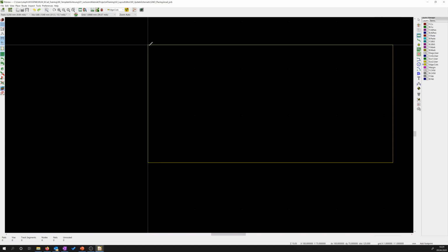The origin is somewhere on the upper left side, counting positively to the right and downwards. So this means we have to make the center of our mounting hole at position 105 and 80.